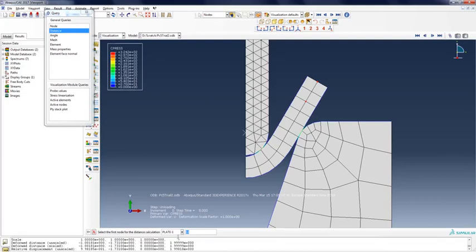This, under the deformation scale of 1, we have the distance in x direction, distance in y, and the total distance. If we want to have in total 90 degree, our distance in x and y should be the same. But clearly the distance in x and y between the two nodes are quite different. In fact, our y direction distance is 1.731, which is much larger than the x direction, which means that we pushed it a little bit too far.